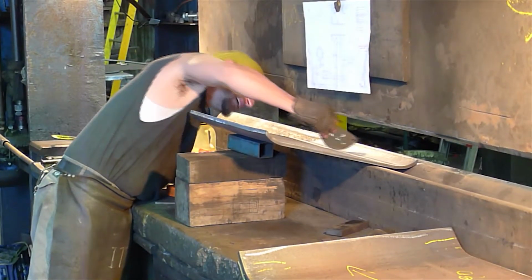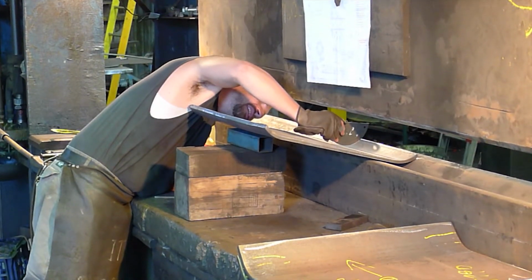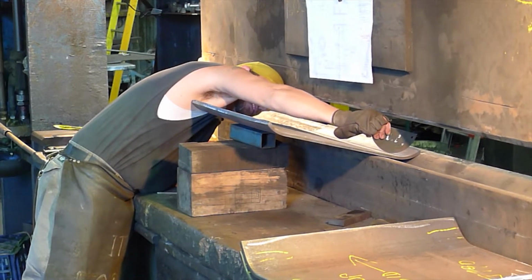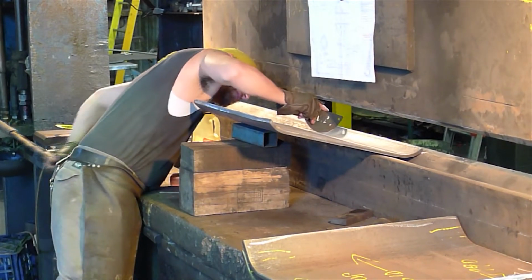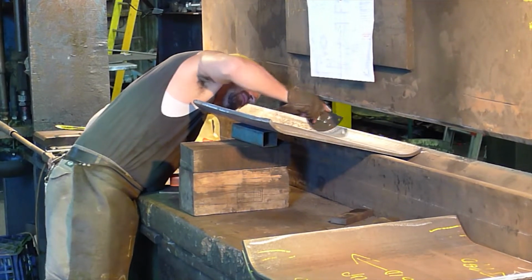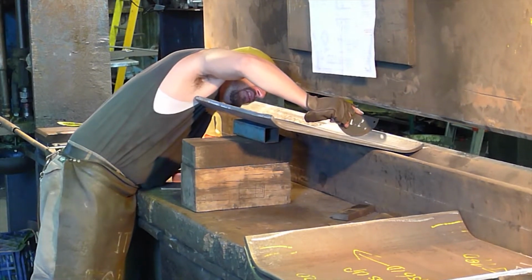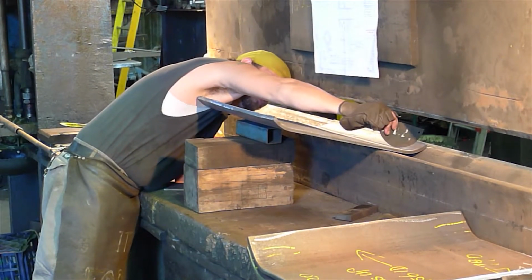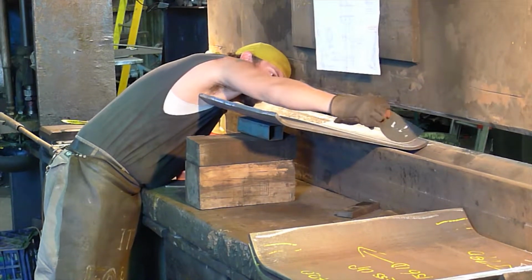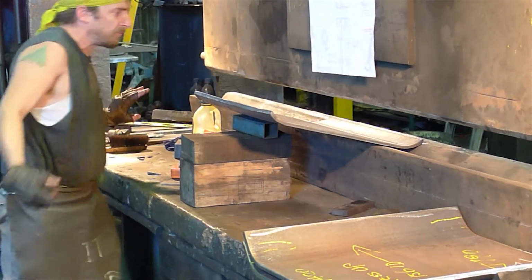Pyramid rollers are unsuitable for forming smaller diameter cylindrical sections. In this case, the hydraulic press is used. This is quite a time-consuming process, as the angle formed must be checked and rechecked for accuracy. The required tolerance in this case is 2mm.